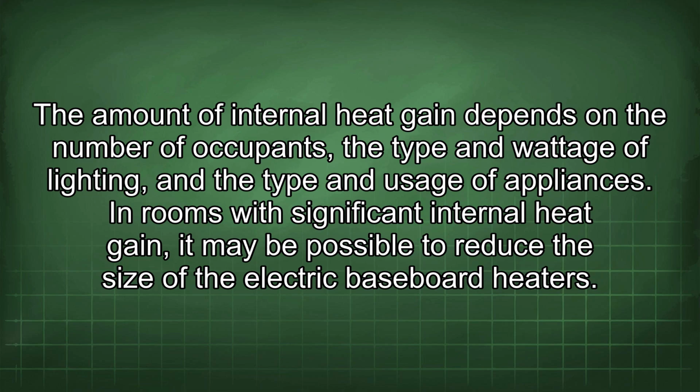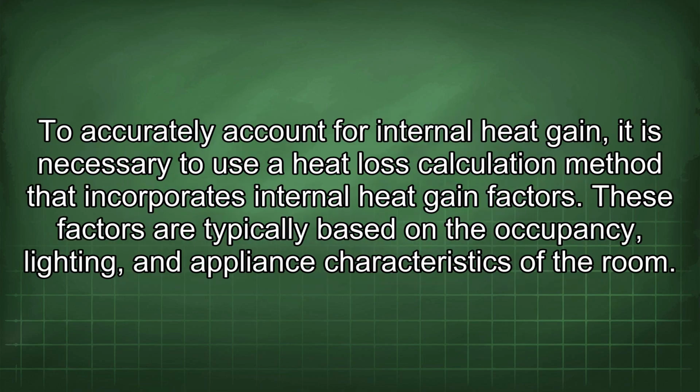In rooms with significant internal heat gain, it may be possible to reduce the size of the electric baseboard heaters. To accurately account for internal heat gain, it is necessary to use a heat loss calculation method that incorporates internal heat gain factors. These factors are typically based on the occupancy, lighting, and appliance characteristics of the room.